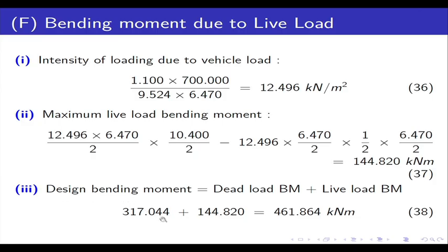But if we go towards more, sometimes 60% is dead load and live load is 40%, and for a long span you can find that the bending moment due to dead load will be further more compared to the live load due to vehicle. So, here you can imagine it is almost more than 50%, 1/3, 2/3 in that particular way we can get it. That means we have to find out the section for this.